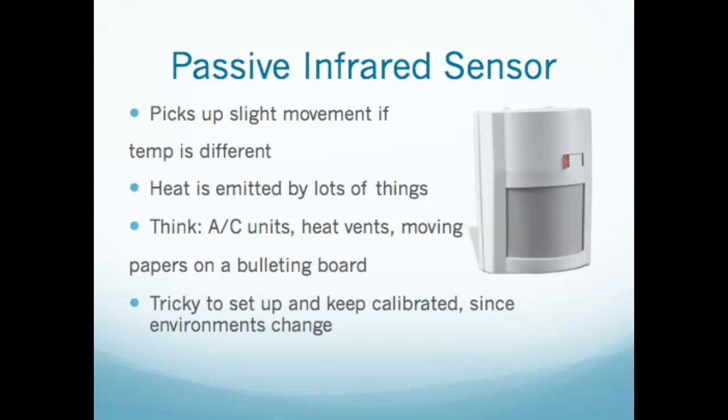So they're tricky to set up and keep calibrated, and you have to remember that environments change. You will put one of these things up and you'll get it calibrated and everything's great, and then somebody goes and throws up a bulletin board, or somebody puts a space heater in, or there's any number of things that can trip these. I hate them because they always tend to give me trouble, and when they don't give me trouble, you think everything's fine, and then you test them out and find out they're really not working very well. You'll see them everywhere. People use them everywhere. I'm not a fan of these. I would prefer to have some type of switch on a door and know that something actually happened, rather than a lot of false alarms.